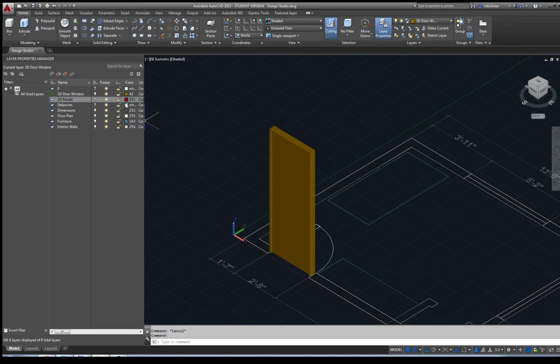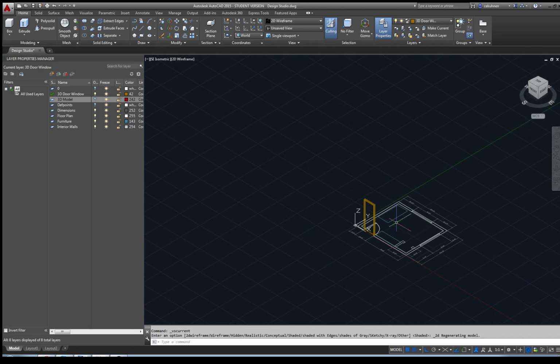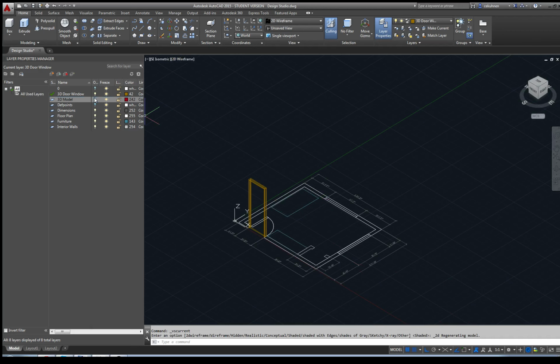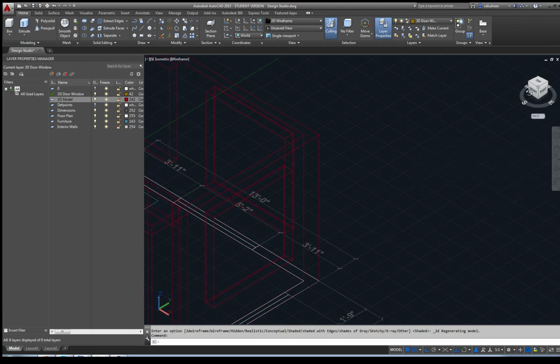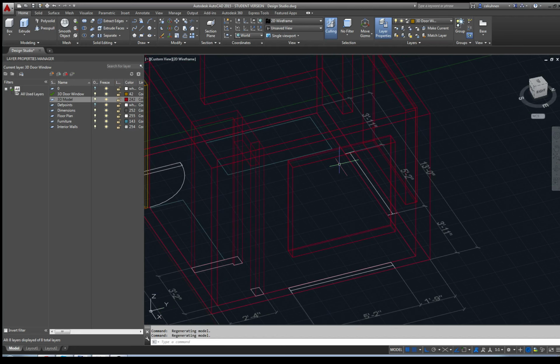So let's maybe take a look at what we could do, for example, with the window. So let's go to wireframe mode. Let's turn this one on, and it might be a little bit more tricky because we again do not want to sketch onto this wall. So turn on snap, click, click, click, click, and click. So there's actually now my window part.